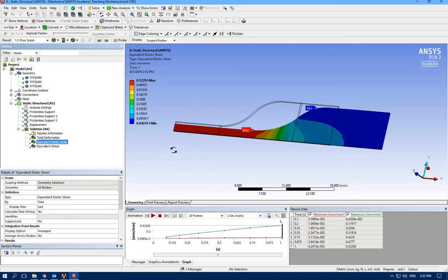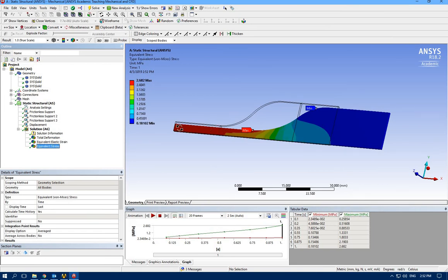And this is the strain. Highest strain is going to be here, and it's pretty uniform. That is why they designed this shape. When we focus on this area, we have uniform strain. Let's see about stress. Again, stress is very uniform here, and it's a good sign. This dog bone shape is a very good shape for this experiment. Okay.